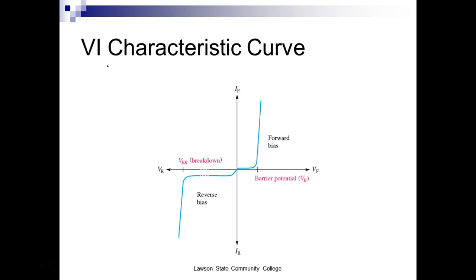So this is a typical VI. What does VI stand for? Voltage current for a regular diode. On the forward bias part, this is going to start conducting. For silicon, it's usually around 4/10 right here. We call this the knee. Once we get above the knee, this is where we want to operate the diode, right there, right? Everybody okay? We use about 7/10 of a volt, but we know that it can actually vary depending on temperature and also current. Now, when we reverse bias this thing,